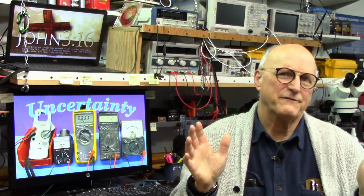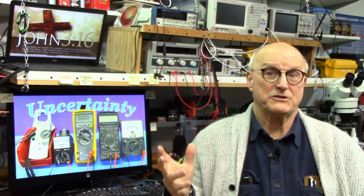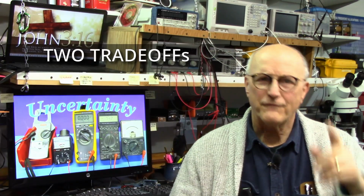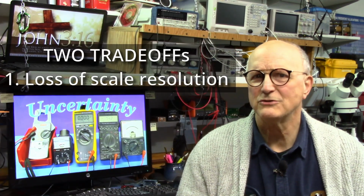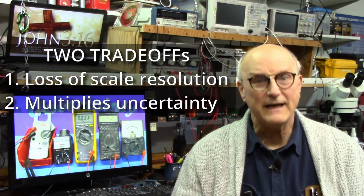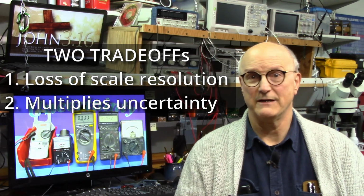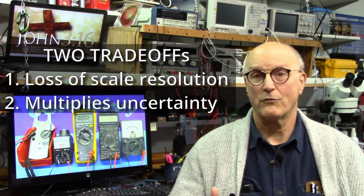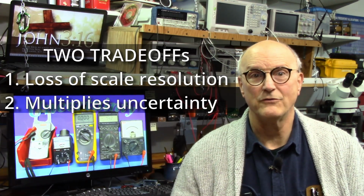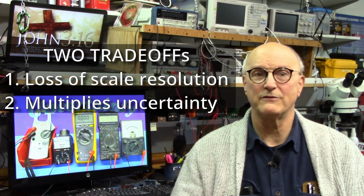Now, you could reduce this effect by using the 50 volt scale, which would give us a 1 megohm input impedance. And that sounds great. It certainly would reduce the loading effect on the circuit. But you have two significant trade-offs to deal with when you do this. The first is that you lose scale resolution, which will affect your ability to read the voltages precisely. The second is that it multiplies the measurement uncertainty from plus or minus 0.45 volts, which you had on the 15-volt scale, to plus or minus 1.5 volts because of the measurement tolerance of the meter itself.